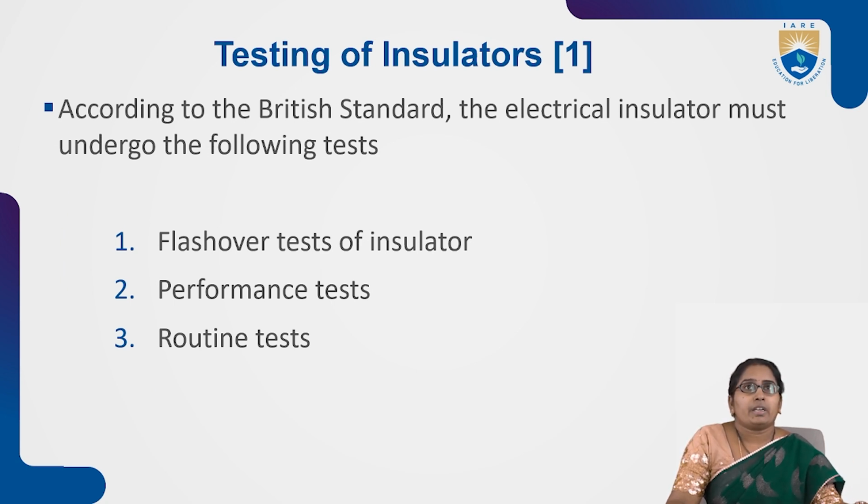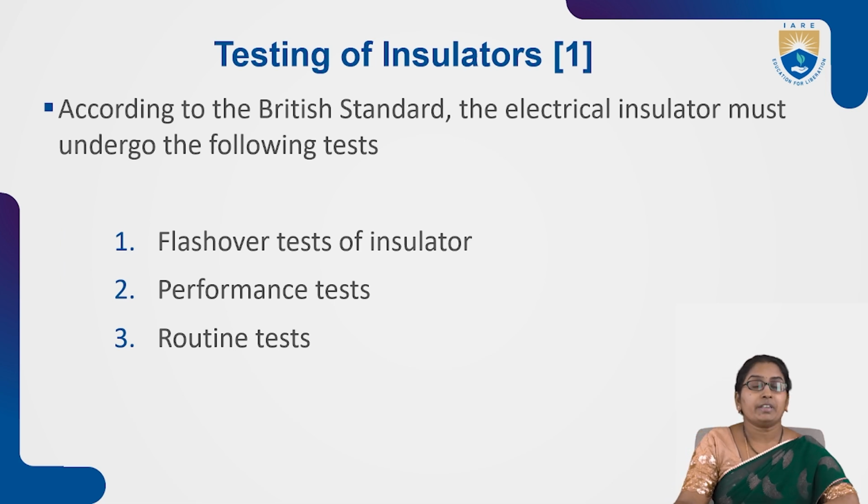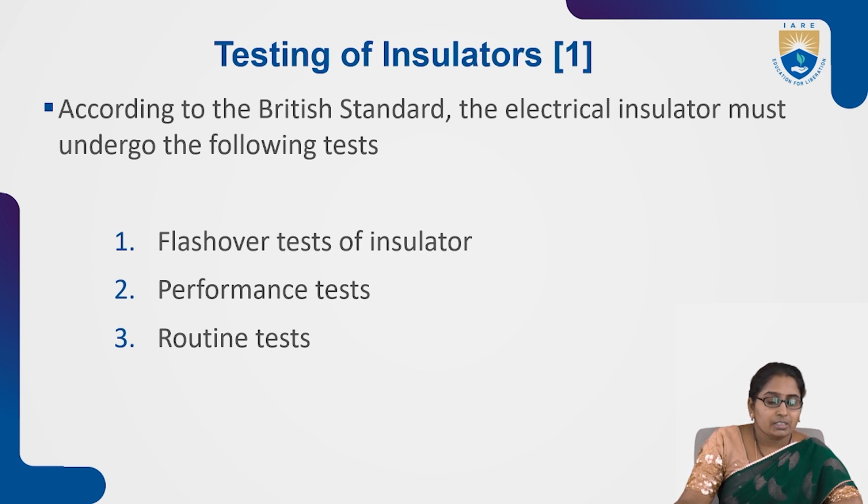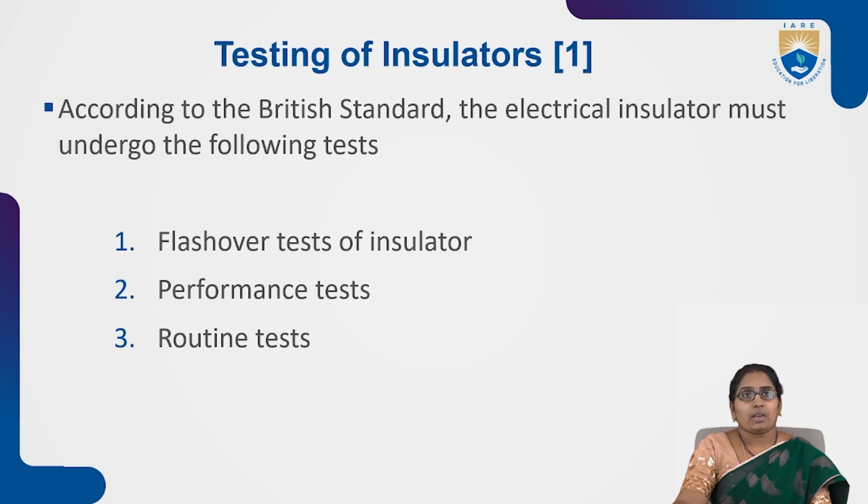According to British standards, the electrical insulator must undergo the following tests. There are three tests that a designed, manufactured insulator should undergo. The first one is the flashover test, then the second is the performance test, and the third one is the routine test. We'll see one by one.